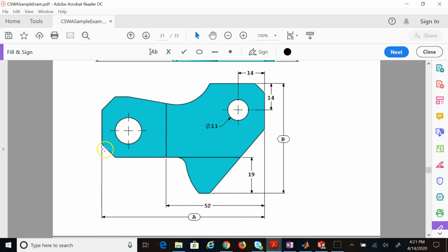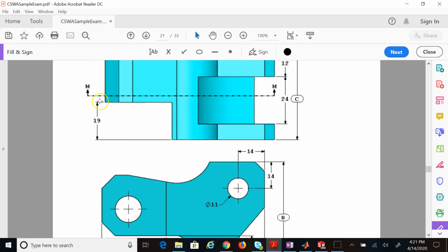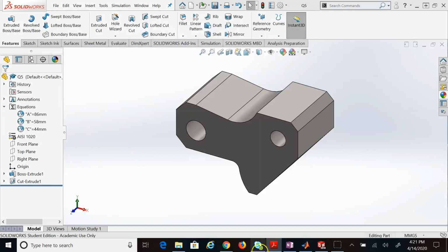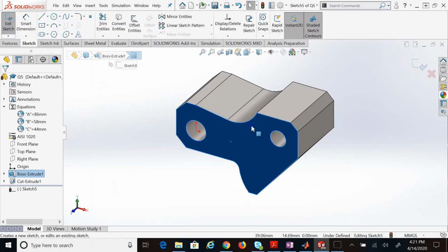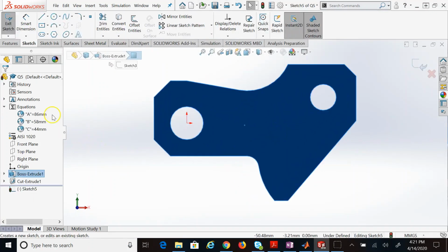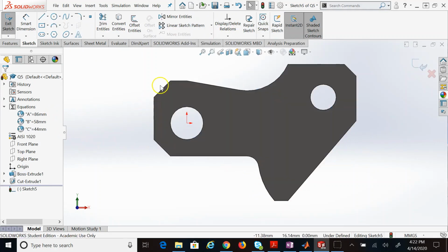So I draw this sketch here using this 52, and then cut extruded 19 units in. Okay, so again I go back here, and this is what I do. I'm not going to redraw on the top of this, I project them. So I click, hold down Control and multi-select as much as needed, this much and this much, and then this much.